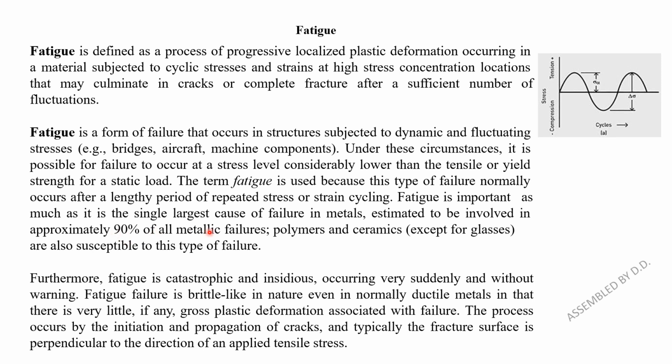Fatigue is important as it is the single largest cause of failure in metals, estimated to be involved in approximately 90% of all metallic failures, and even some polymers and ceramics also, except glasses. Fatigue occurs very suddenly and without warning. Fatigue failure is brittle-like in nature, even in normally ductile metals, in that there is very little gross plastic deformation associated with the failure.